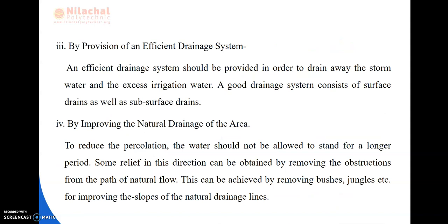Next, by provision of an efficient drainage system. An efficient drainage system should be provided in order to drain away the storm water and excess irrigation water. A good drainage system consists of surface drains as well as subsurface drains.